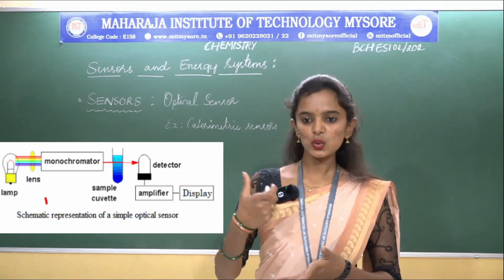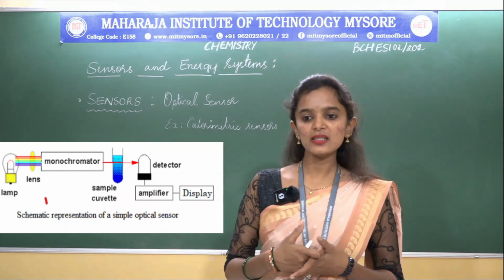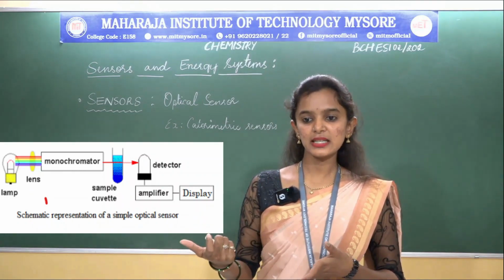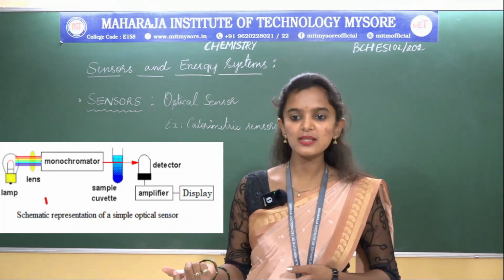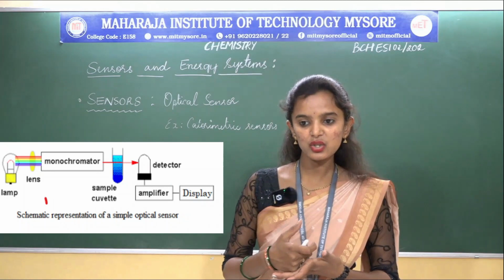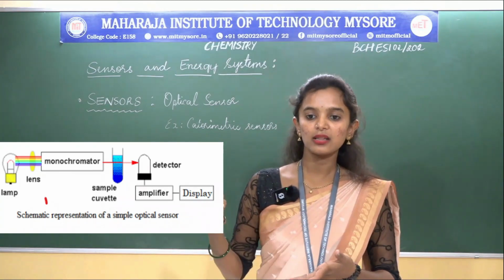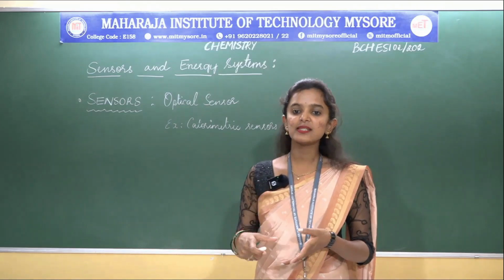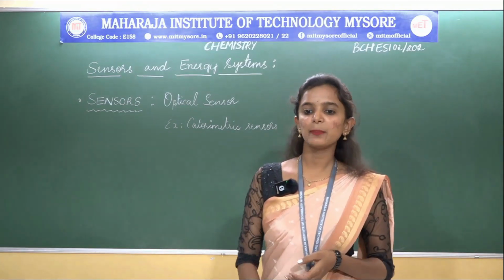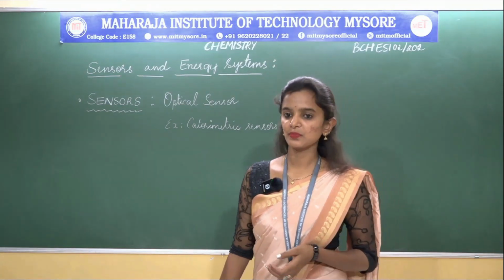The light source generates an intense radiation signal which is needed to detect the optical properties and the molecular recognition element which is in the sensor. The amount of absorbance can be governed by the Beer-Lambert law.